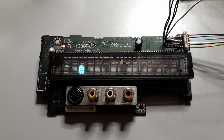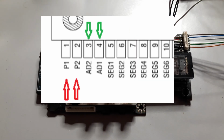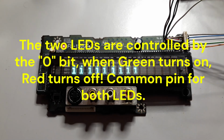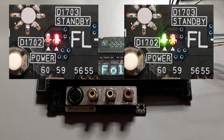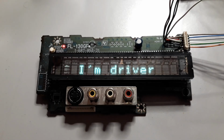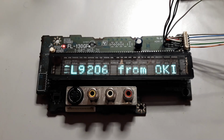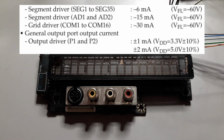The driver has two general purpose input-output pins marked as P1 and P2 that come directly from pins 1 and 2, and on this panel they connect, at least one, to control two green and red SMD LEDs. It is also worth highlighting the presence of the two additional anodes on pins 3 and 4 labeled as AD1 and AD2. In total, we are able to control 35 segments distributed across 16 grids.